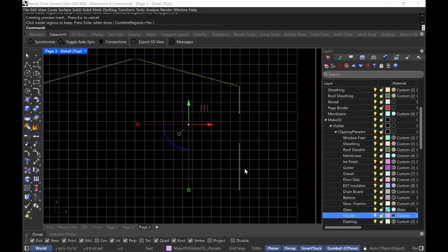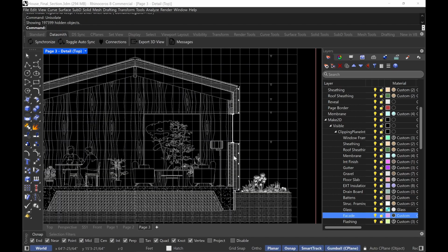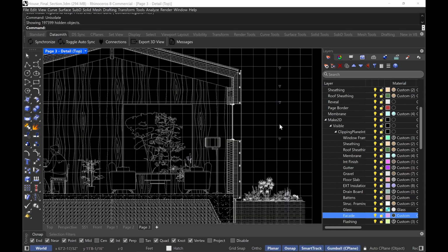So it's really important you do that methodology. If you do not have things that are closed and bounded, you have two options. Again, you can either close it off by adding line work to it, like for your installation, you can just do rectangles and hatch those rectangles, or you keep things open and hatch them within the boundaries they are, right?